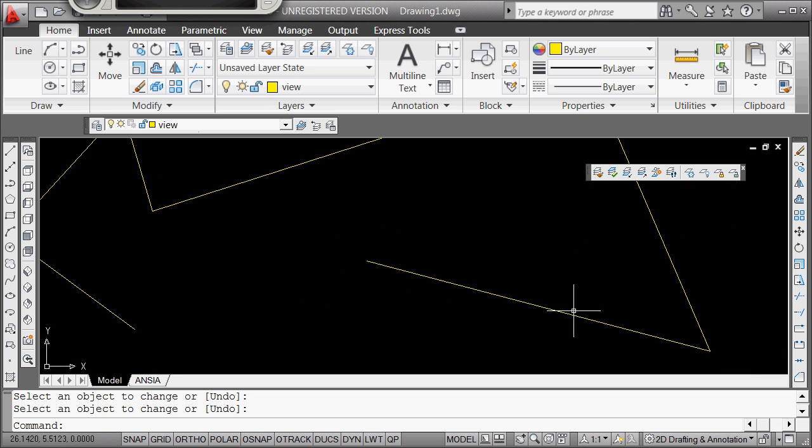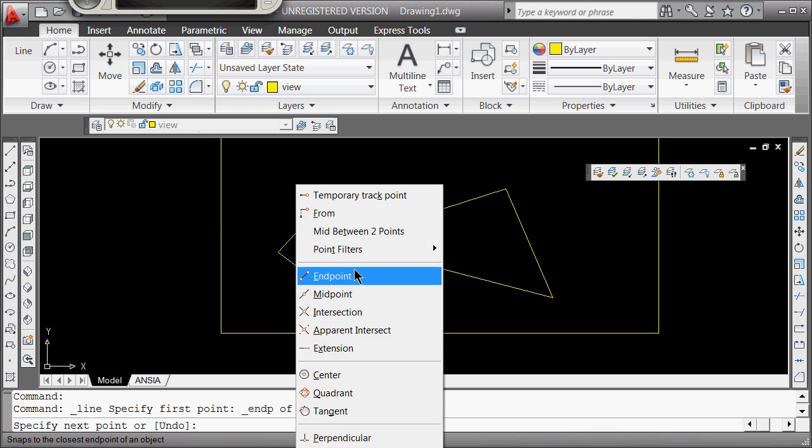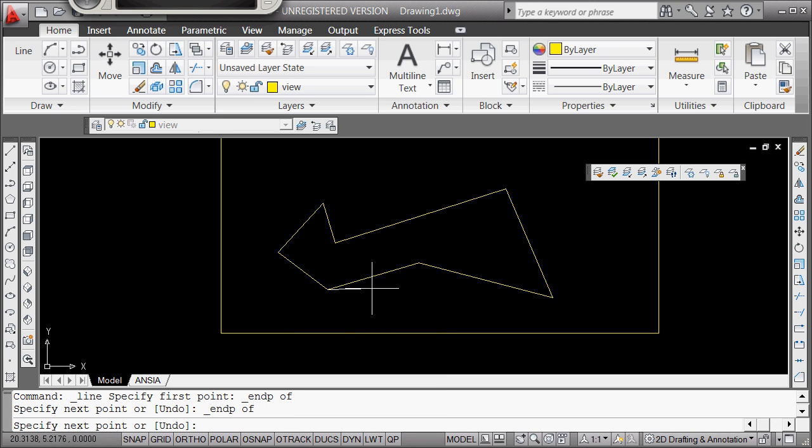What this did is I grabbed either side of the midpoint. It figured out which side to push the line out with. Finally, again, the most important thing we have in CAD is that we learn to do line, shift right click, endpoint, to shift right click, endpoint, and we have that piece drafted in less than 10 minutes.